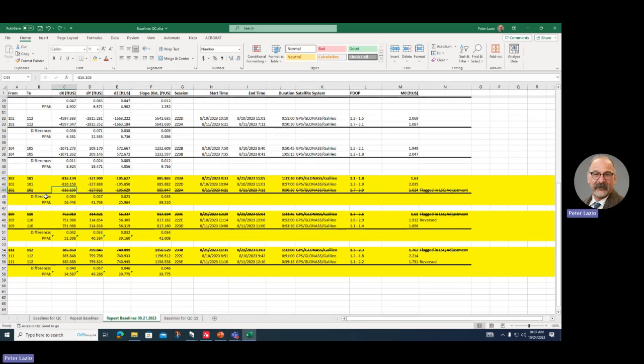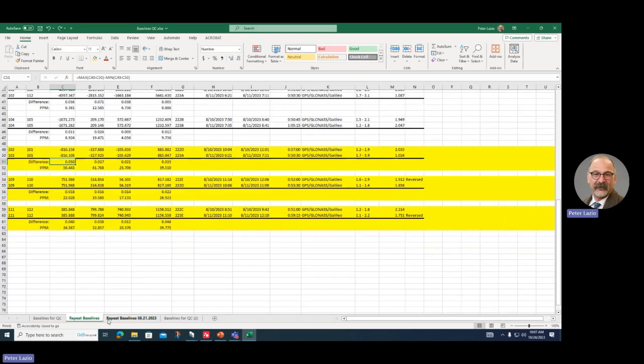But I was combining this with total station measurements too. Depending on how much time you have, you could do an adjustment with just the GPS and the total station and try to tease out which is the best baseline also. But there's a limit to how much you can figure out sometimes. So this was after we had to go back out and re-observe.